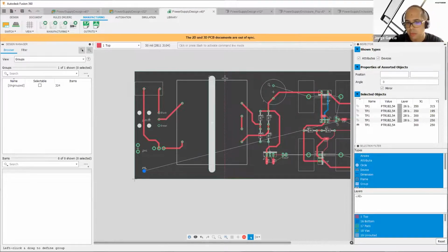In Fusion, we're just defining the contour and then it fills. So you always have maximum resolution. So keep that in mind. If you do export the Eagle file, I do recommend just taking a quick look, making sure your polys are how you want them to be before you send them out, because that is the one big difference in the output between Fusion 360 and Eagle.